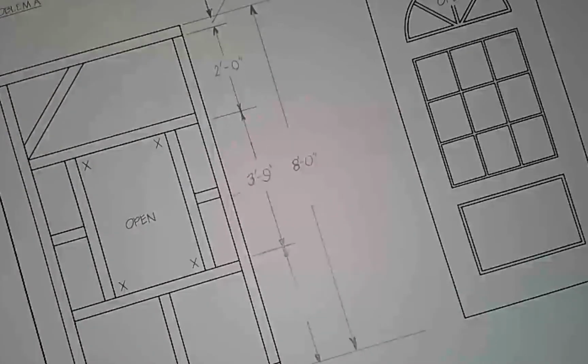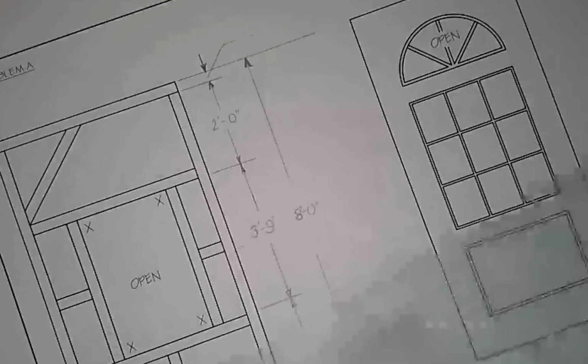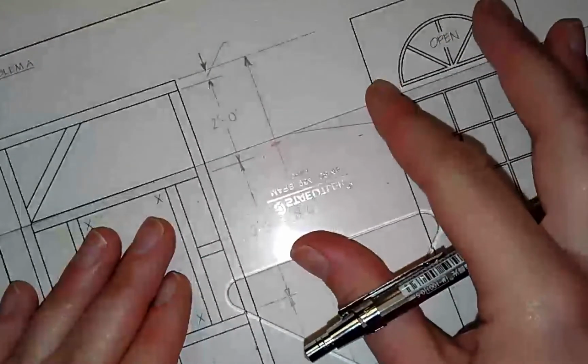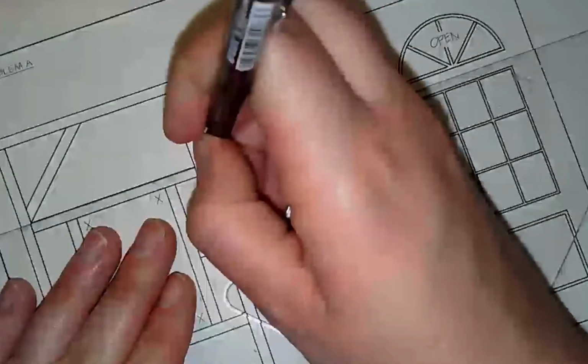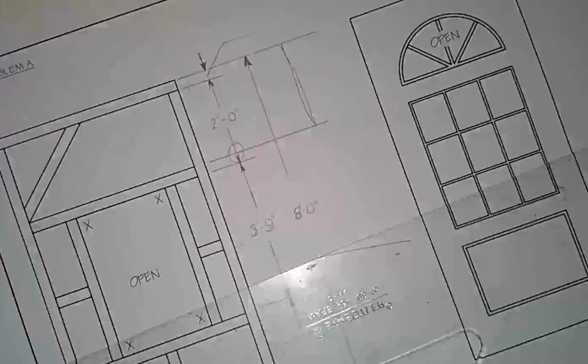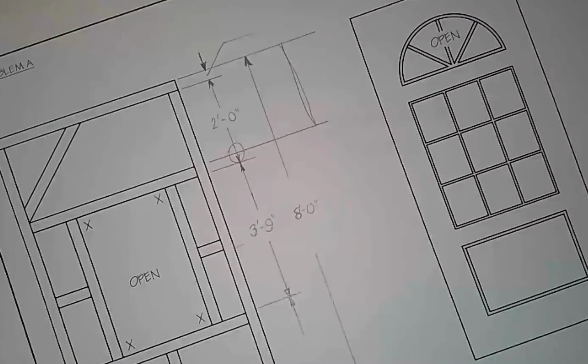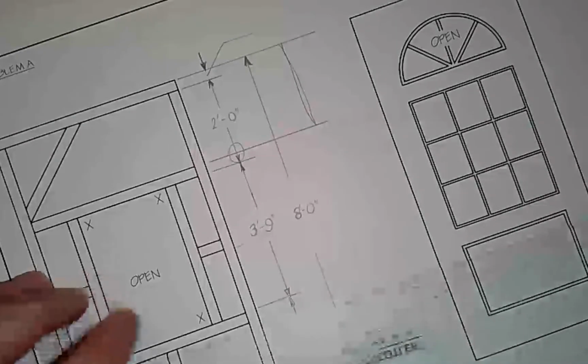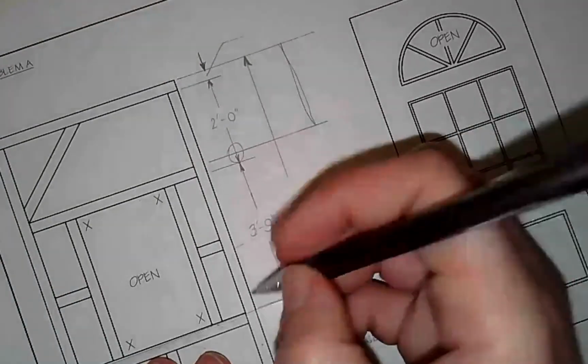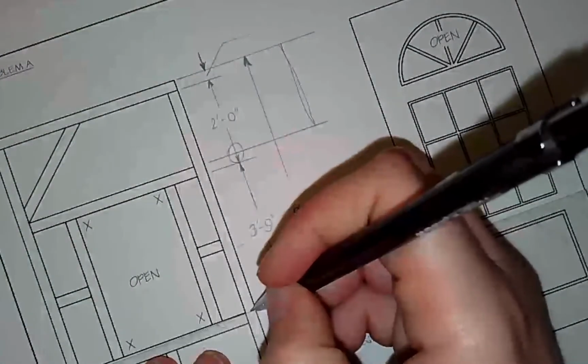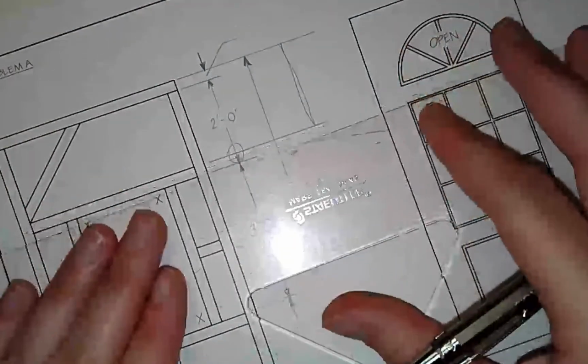So a thing that would be a no-no, that would be bad, would be to take this dimension line and crisscross every which way and do a dimension out here, okay? Because then we have this intersection that's confusing. Sometimes you have to do that because things are at odd angles to each other, but it's not ideal. So the other thing I'm doing, right, is I'm actually pulling from this point, right? So instead of leaving that extension line there, it should cross the object line to identify the actual points that they're pulling from. So that's my mistake, right?